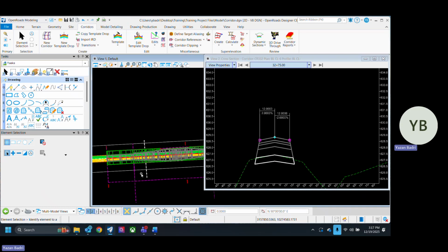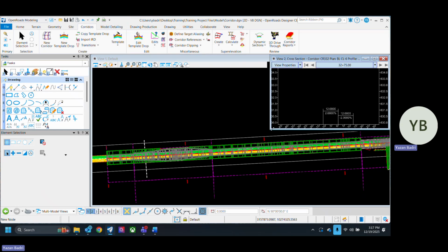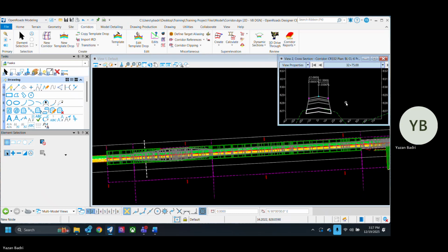Ooh, wow. Yeah, this is probably the most complicated one of them all, especially when you have different sections in the pavement. Let's say you have like a 3% shoulder, or those areas where you're doing 3% and then 2%, or 2% and 3%. The next question becomes, what is our objective? Is it to correct and bring things into compliance? The super. So what do our scope and money allow us to do, if she's adding a shoulder or right turn lane, or if it's a brand new project to correct every deficiency? Yeah, that makes a difference. Very interesting. It is.